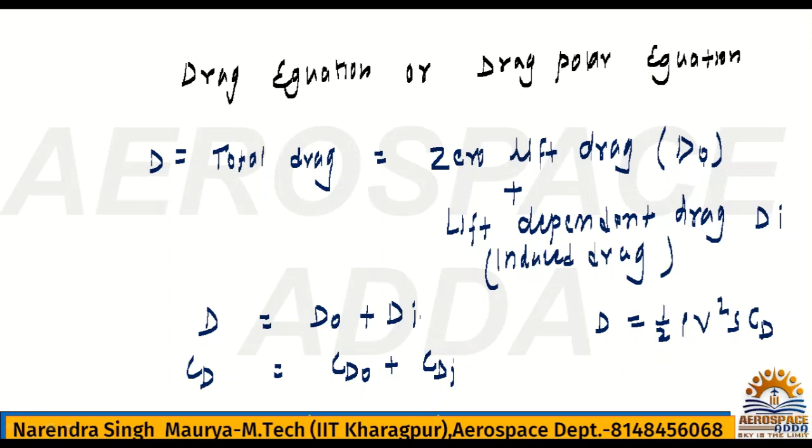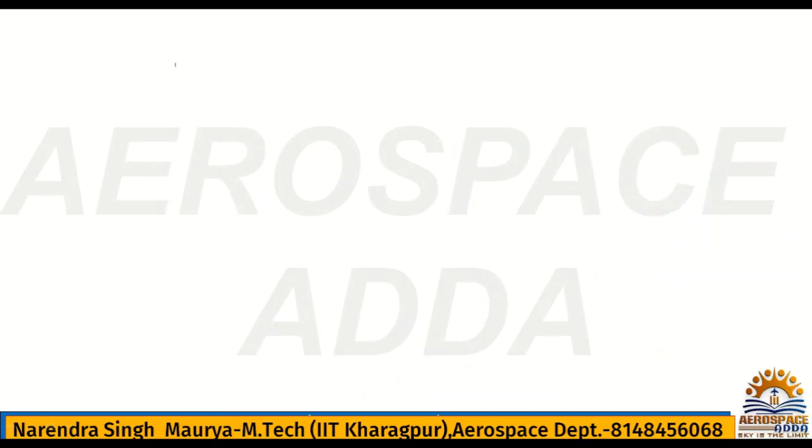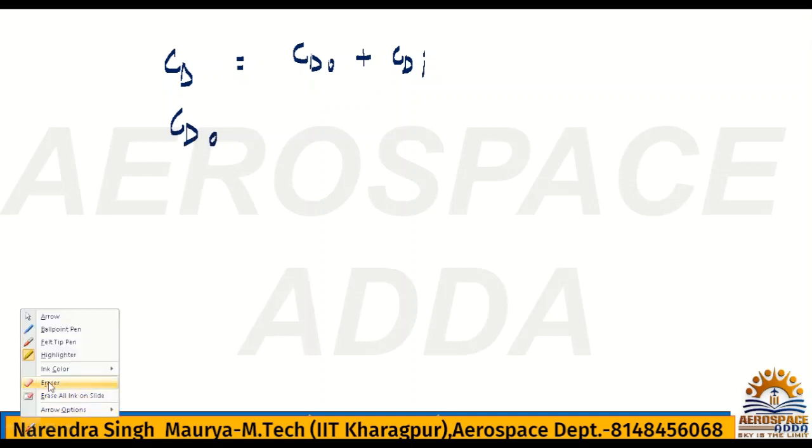Use this formula, and then half rho V square S will be cancelled out, as it is common for all. So we will get CD equals CD naught plus CDi. This is the total drag coefficient. CD is the total drag coefficient.